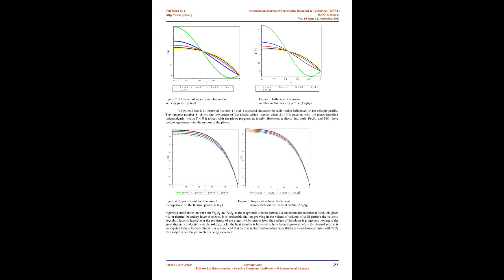The effective dynamic viscosity of nanofluid is given by μnf equals μf over (1 minus φ) to the power 2.5, where φ is the solid volume fraction of nanoparticles. The effective density, thermal diffusivity, and the heat capacitance of the nanofluid are provided as follows. Results and discussion.